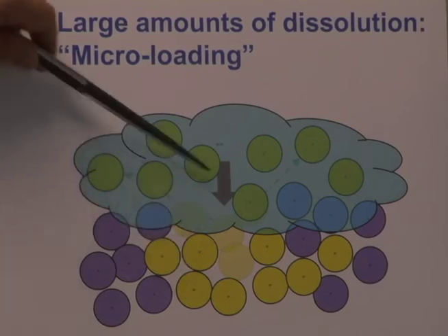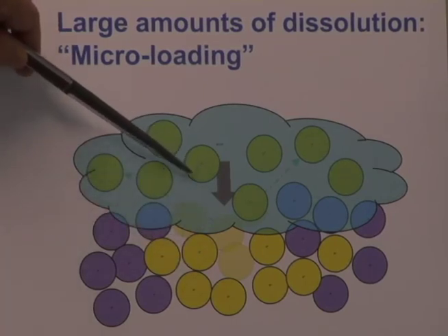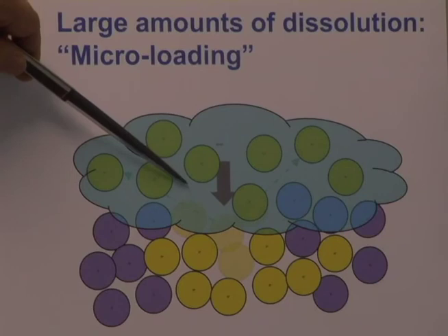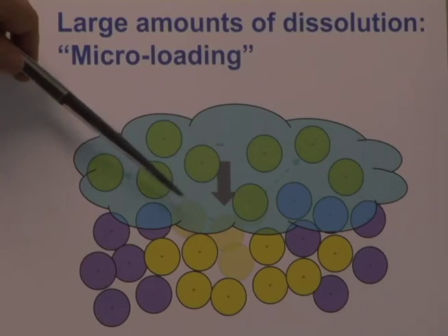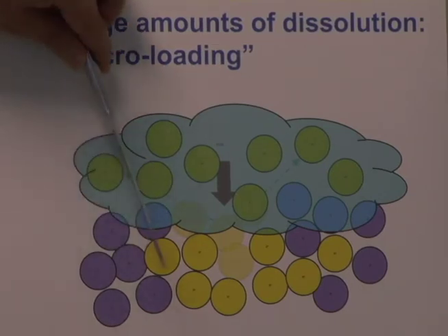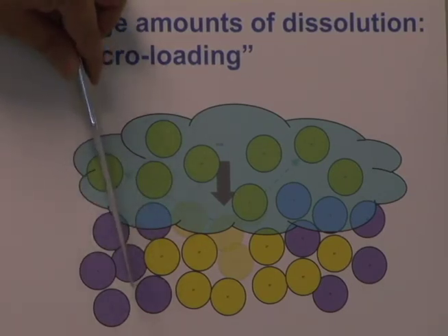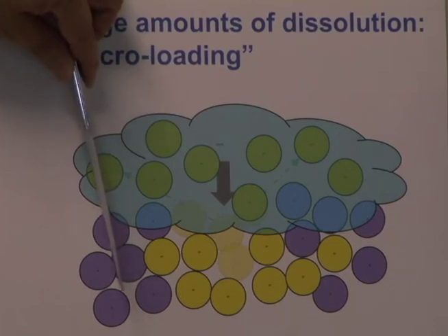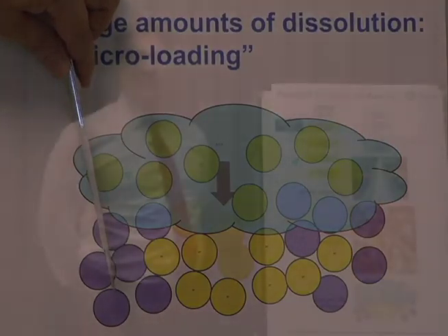Large exposures then result in a significant percentage of resist in this local gel, effectively blocking further resist from dissolving. This impact will be seen by slowing down the slowest dissolution rates first, which is that of the lateral resist development. That results in an iso versus dense region print bias observable on reticle.